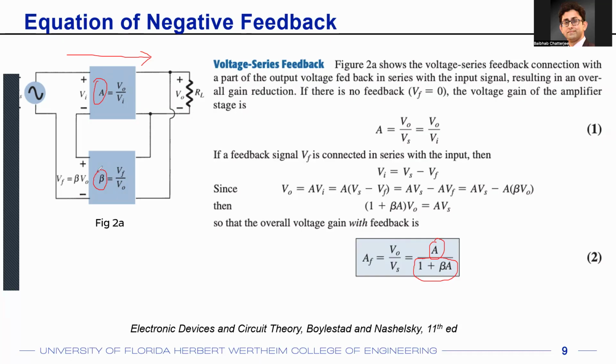Right? And we also discussed in the last lecture that it's easier to stabilize the beta network because it's usually a ratio of resistances or a ratio of capacitances. We'll see examples. You have already seen some of those examples in your 3111, which I would like to relate with this concept. Now, the beta network is usually a resistive network, which means that the ratio of resistors generally stays constant across PVT.